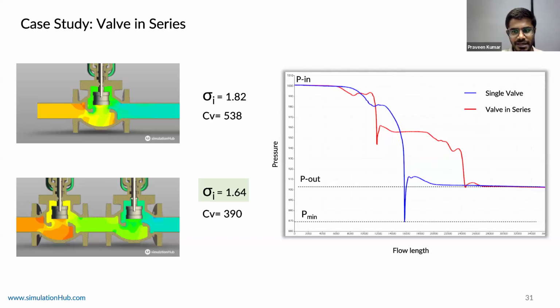Okay. So I'll take this question. Naveen, I'll just again specify. There are two terms, right? Incipient cavitation index and cavitation index. So incipient cavitation index is stamped for that particular design and opening, so that is constant. Cavitation index is related to the operating condition. So if you want to compare two designs, you always compare incipient cavitation index, and that incipient cavitation index should be less. Why should it be less?